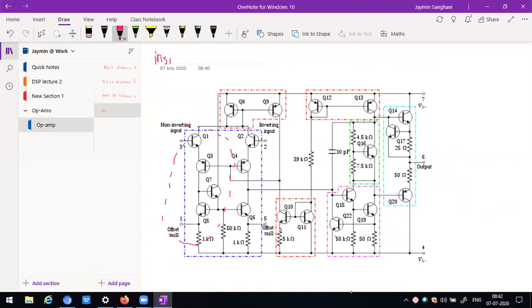Inside the op-amp, see this is the first transistor, this is the third transistor, second transistor, fourth transistor. This is known as the dual input balance output differential amplifier. Each transistor has its own current gain beta. Now I will explain why current gain and voltage gain are improved inside the op-amp. This is another transistor with another gain beta. Beta can be multiplied here, so we get beta squared.